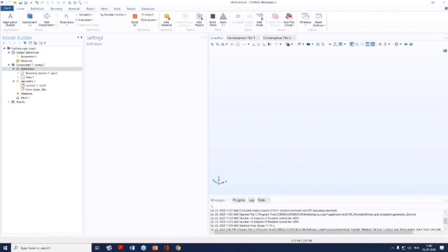What is the significance of these two tolerances? We just discussed some time back what is the difference between the relative repair tolerance and what do you mean by the absolute repair tolerance. When you provide the absolute repair tolerance directly, that tolerance will be used to see which object should be merged. Whereas if you provide the relative repair tolerance based upon the geometry, the absolute tolerance will be calculated and accordingly the geometry will be treated.